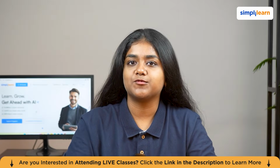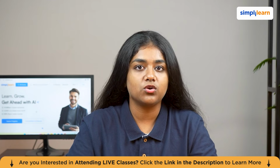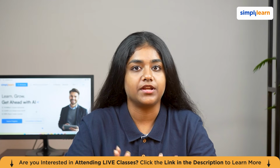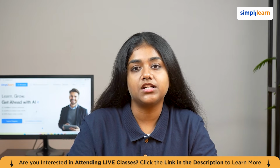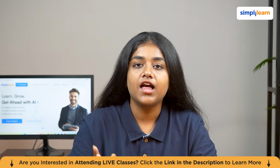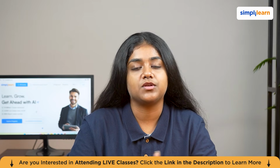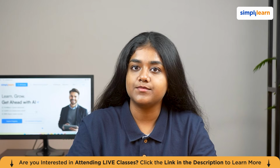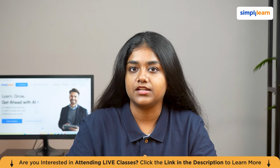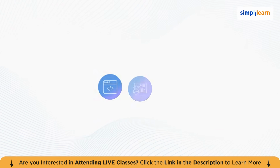So with that, we have come to the end of this module. In this module, we covered how bias is not always consistent across the gauge's full operating range. We explored how linearity analysis evaluates bias at multiple reference points from low to high and uses regression analysis to determine whether bias changes as measurement value changes. A flat regression slope indicates good linearity, while a steep slope signals that the gauge behaves differently at different points in its range and cannot be uniformly trusted.